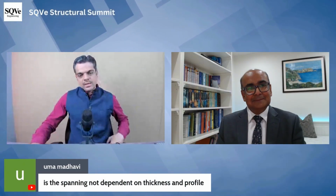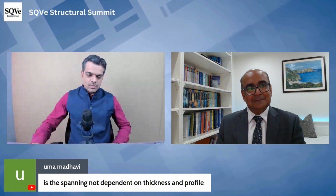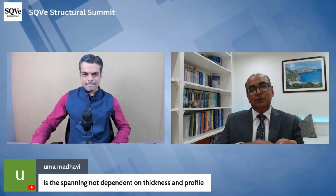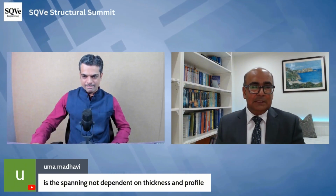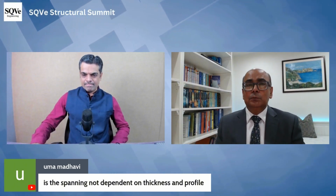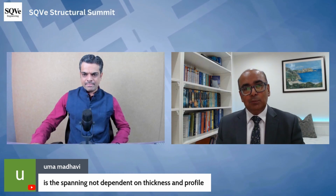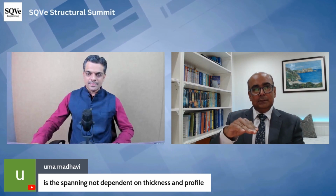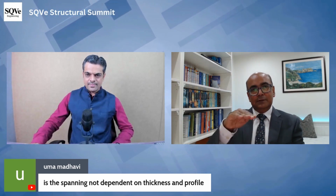Okay, one question: is the spanning not dependent on thickness and profile? It depends on the thickness of the deck. It depends on the profile type as well. So as I mentioned, 50 millimeter will not have much spanning capability, only 2.5. On the other hand, 146 millimeter will have a lot, in my view. The load span table would give a lot of depth of concrete. I would not use a lot of deep concrete.